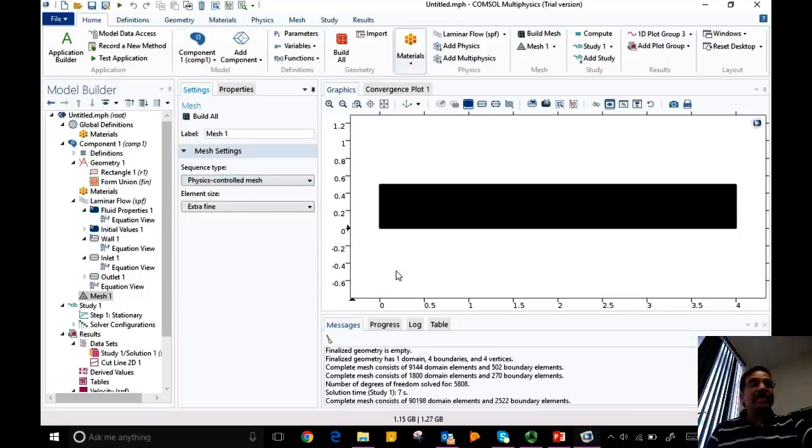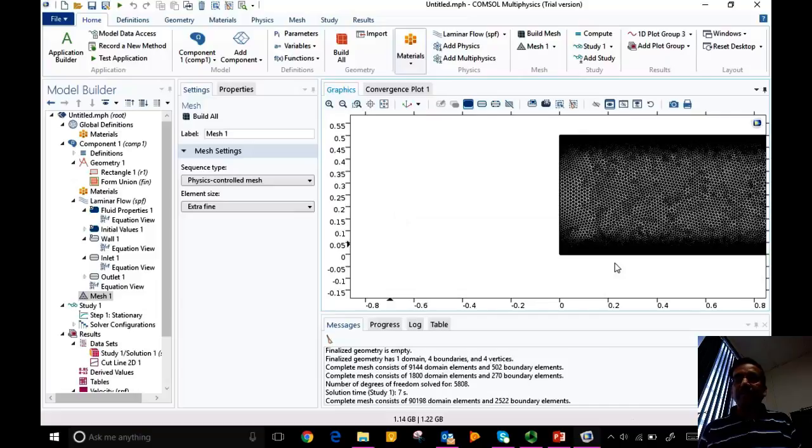Yeah. So now you can see the mesh is really very, very fine, and I have 90,000 mesh points. Okay, so it's going to take a long time to solve this, but you can see how the boundary looks. Really fine. So you're going to localize that discontinuity effect to a very small effect. So you will get accurate results here in this region. Whereas previously, if that was the mesh size, the next point is also going to be an error. Right? So that's how you localize the singularity impact.